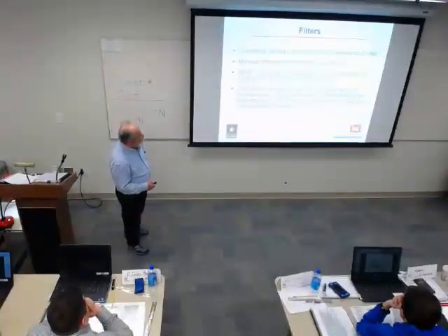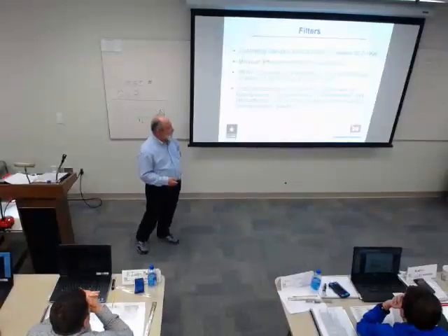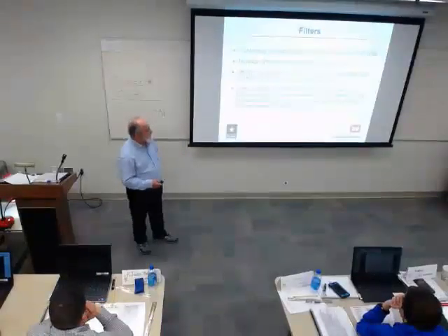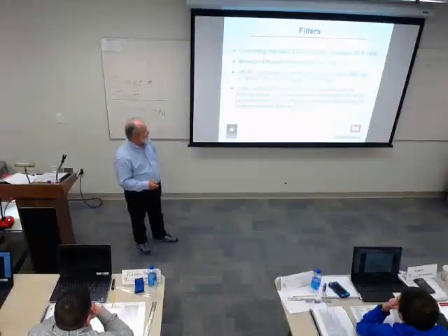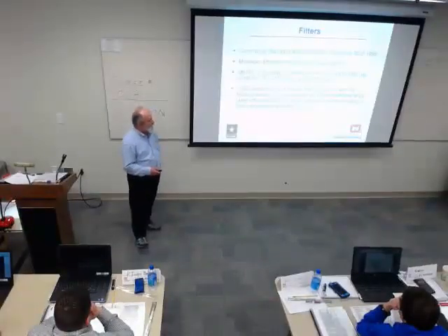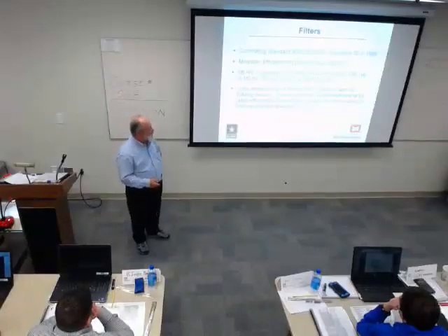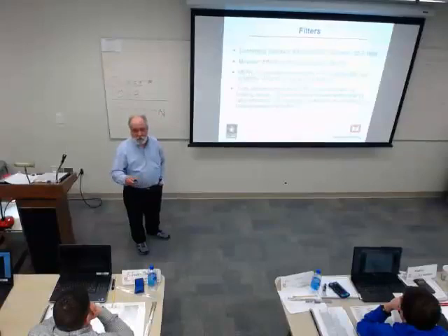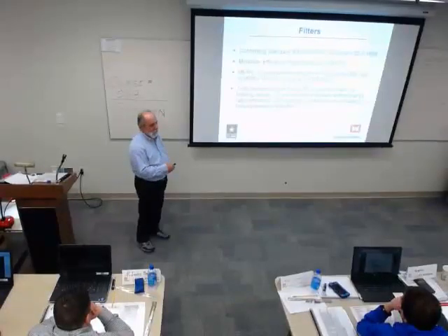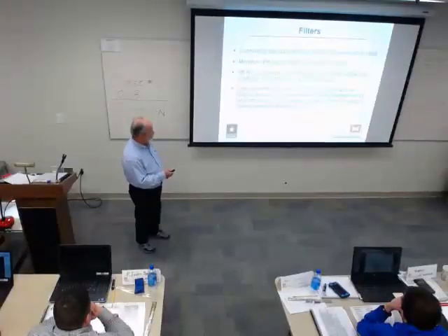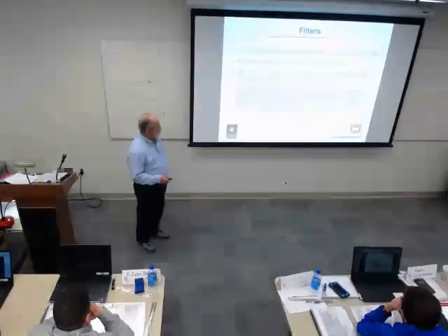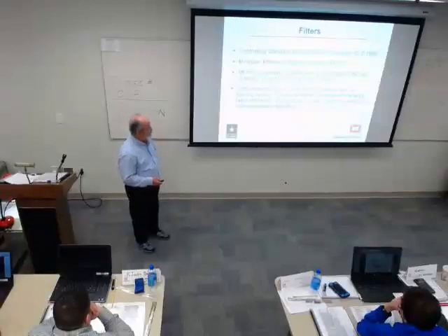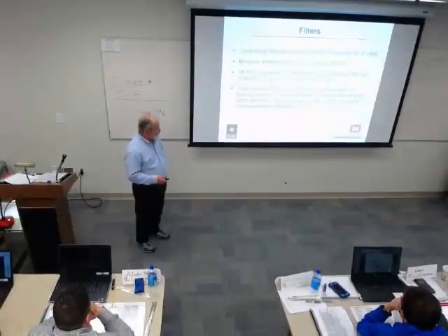Filters: Standard 52.2 is the controlling one. MERV stands for minimum efficiency reporting value. MERV 1 is really low, we don't use that. Well, we might under certain circumstances, but in normal HVAC use, we wouldn't use that. There are conditions in which we suggest that for a certain application. It goes up to a MERV 16, which is a 95 plus ASHRAE filter.